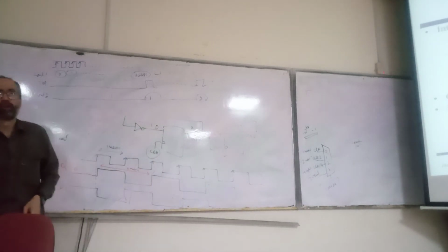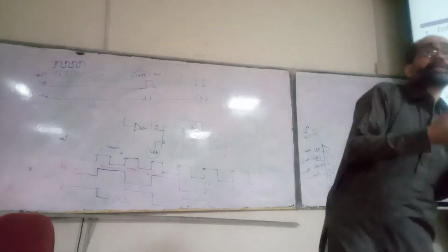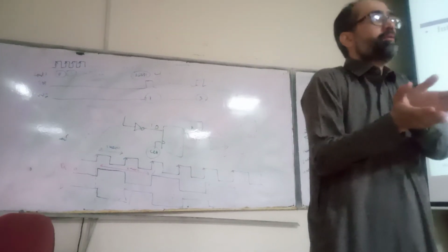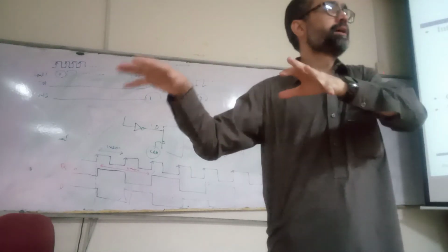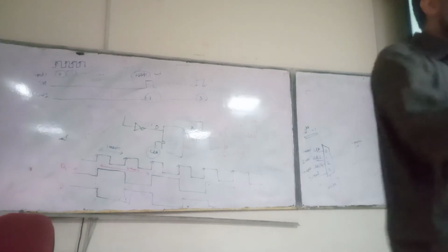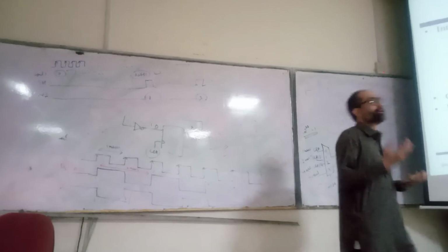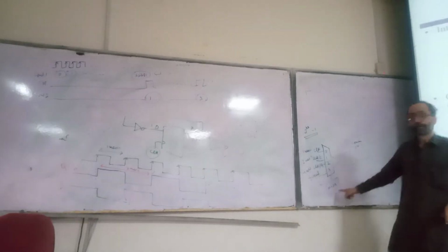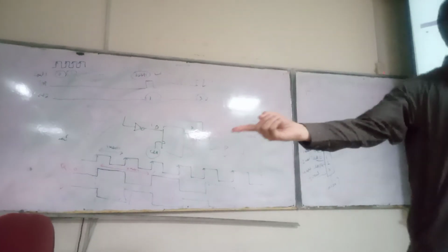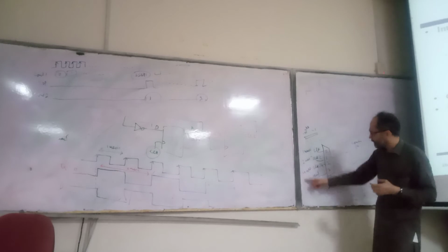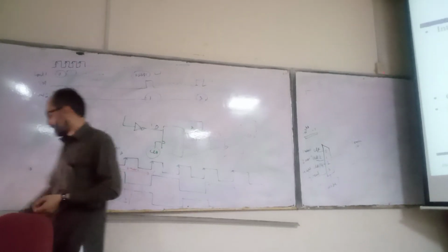As a hardware designer, you can design a multi-purpose counter, a timer structure that can not only count the number of clock events, but with different flavors. Different flavors include different ranges and different resolutions. Depending on the requirement of the user in terms of range and resolution, you can configure it through the mode register. This mode register can be controlled by a microcontroller or a microprocessor. And then you can also configure it as an event timer in which you can count the number of events.